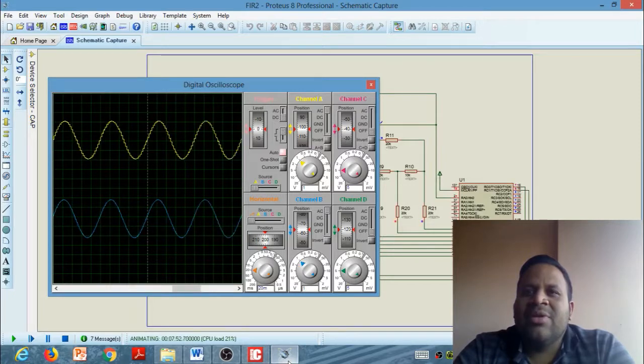The offset parameter is set at 2.5 volts and the amplitude parameter at 2 volts. This action prevents the generated signals from leaving the permitted range. For simulation purposes, the frequency parameters can be altered to the developer's liking.